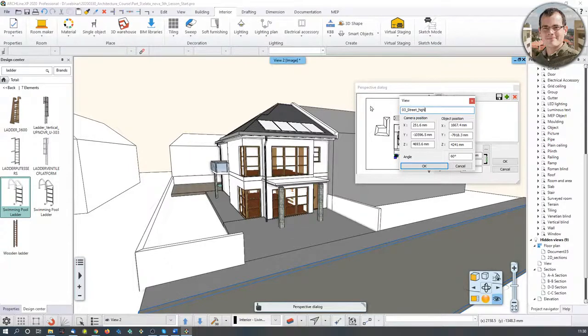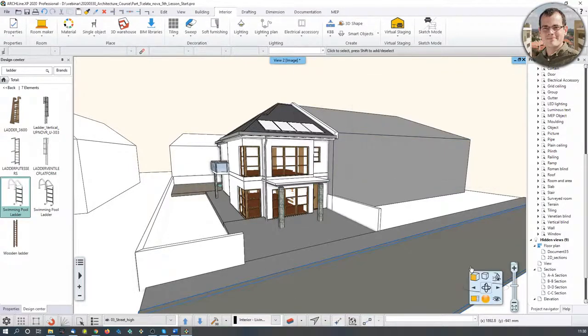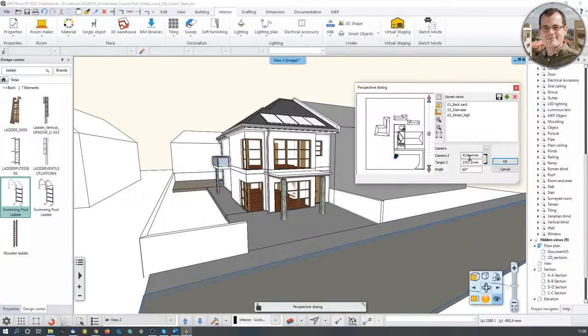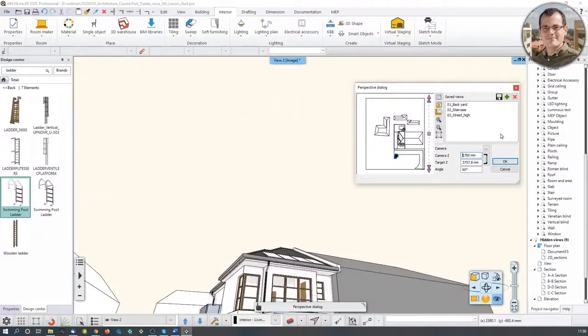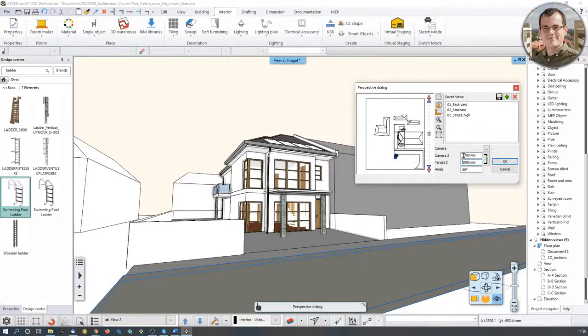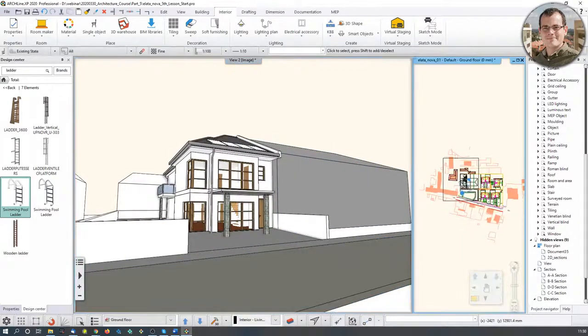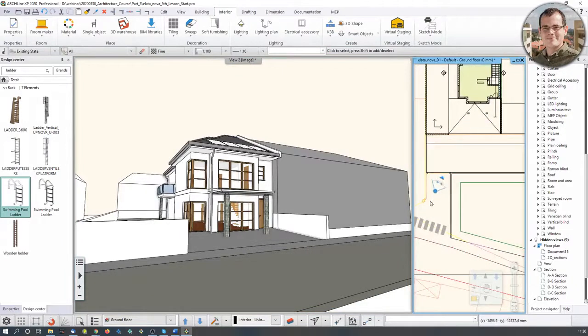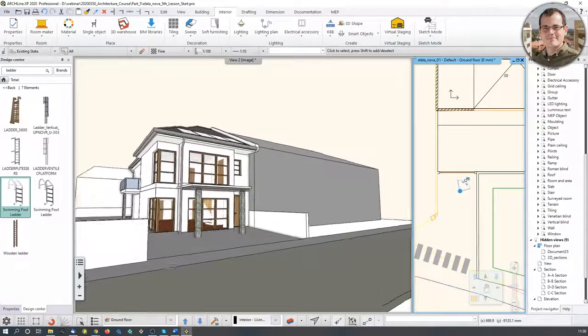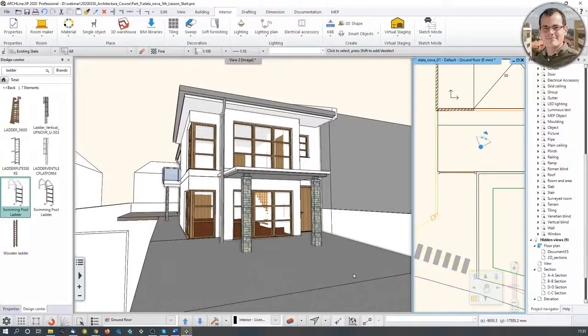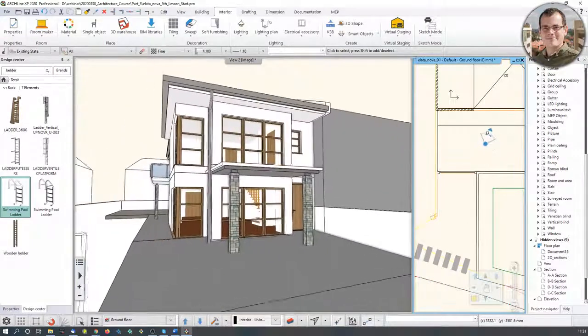street high. And I'm doing another one where I'm looking at from a human-sized angle from 1700, and I'm looking at 2000 millimeters. Sorry, I managed to type something else. So like this. I think this is a bit more natural. Maybe this time I need to come a little bit closer. Before I save it, let me show you how to fine-tune your visuals again. So if I go to the 2D and I see this tiny marker, this is me. So that's where I am, and that's where I'm looking at. So if I grab onto this triangle, I can move myself a little bit closer to the drawing, like that. By the way, you can rotate it as well, but I think this will be fine.